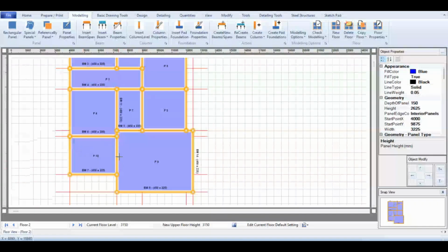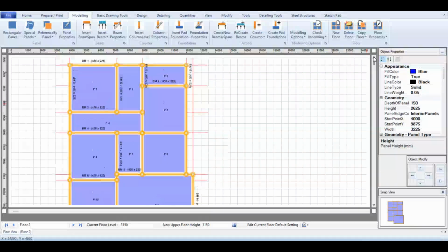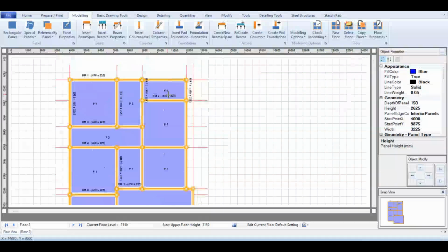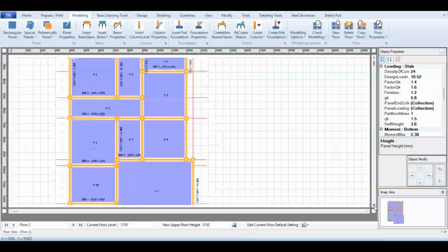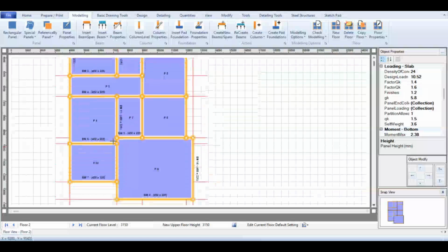As a structural engineer, you're supposed to know where to place your columns. Then you will check. As you can see, from here to here there are 2 columns, but you need to omit one because they are too close. Both of them are working for a particular load.